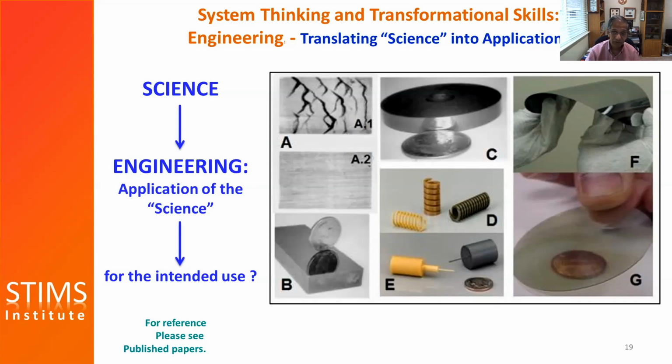You can grind ceramics to a very thin diameter, as shown in E, without any end support. You can do that because the force per grain and the kinetic conditions are so good, and because the material has its own inherent strength. You can grind a silicon wafer, which is a brittle material, and bend it like a plastic sheet of steel. You can grind a sapphire so plain and so good in surface quality that it becomes transparent.